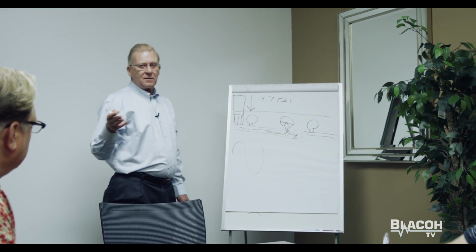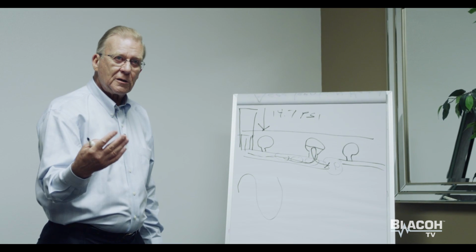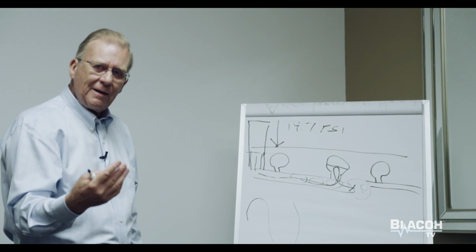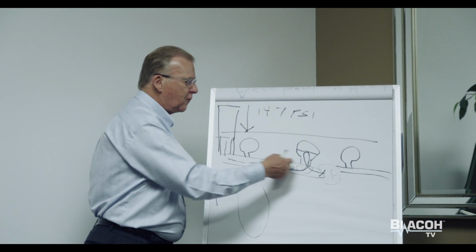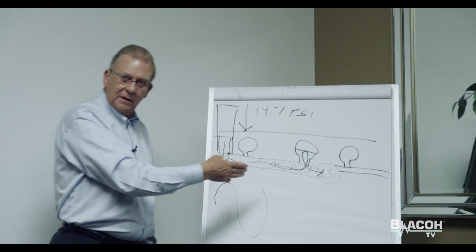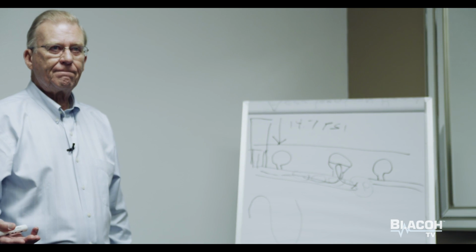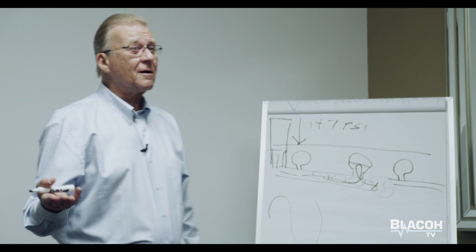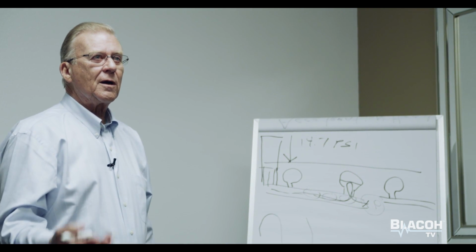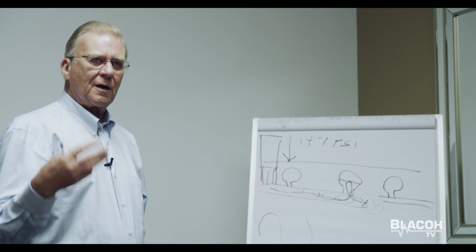So we recommend within 10 pipe diameters of the pump's inlet or 10 pipe diameters of the pump's discharge. But it can't be effective if it isn't acting on the full flow volume of the liquid in the system, okay? Size, location, and charge. Size, location, and charge is exactly what's required, not only to minimize pulsation, but to control and reduce acceleration head.